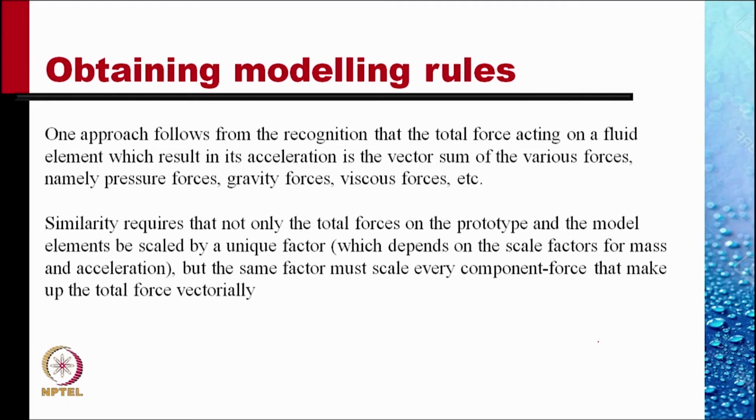One approach follows from the recognition that the total force acting on a fluid element which results in its acceleration is the vector sum of the various forces such as pressure force, gravity force, viscous force, etc. Similarity requires that not only the total forces on the prototype and the model be scaled by unique scale factor, which depends on the scale factors for mass and acceleration, but the same scale factor must scale every component force that make up the total force vectorially.